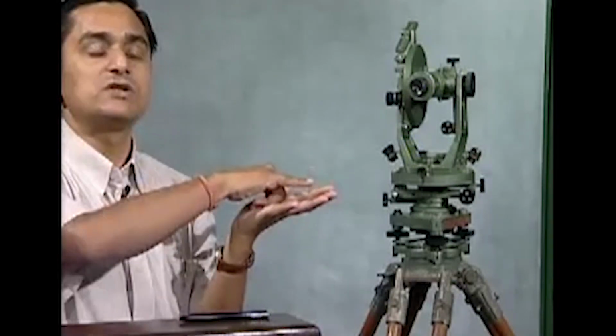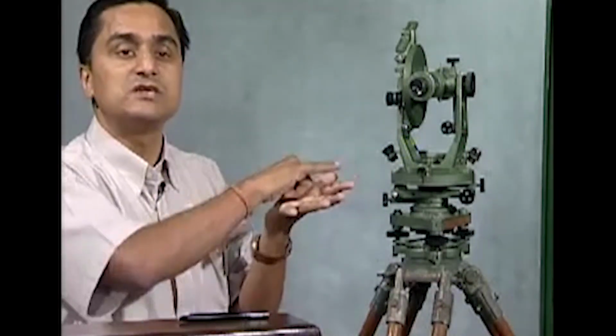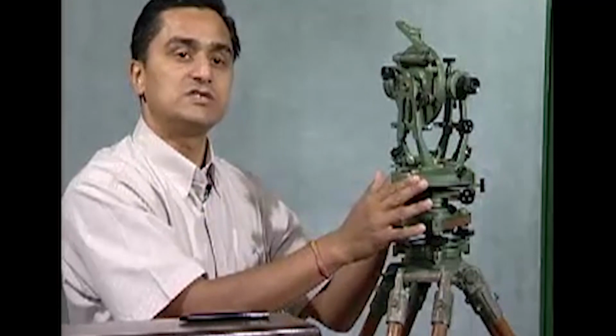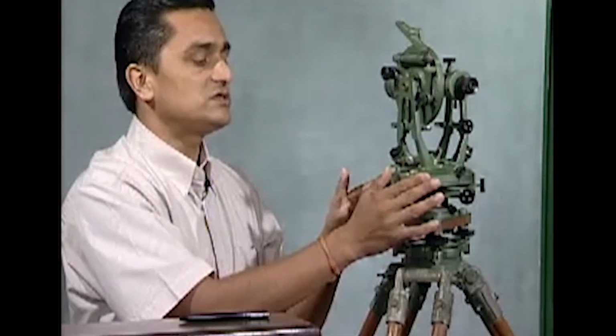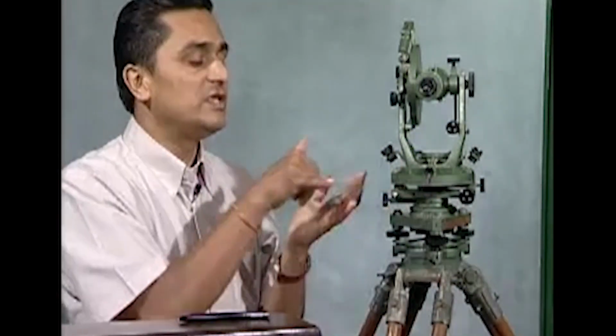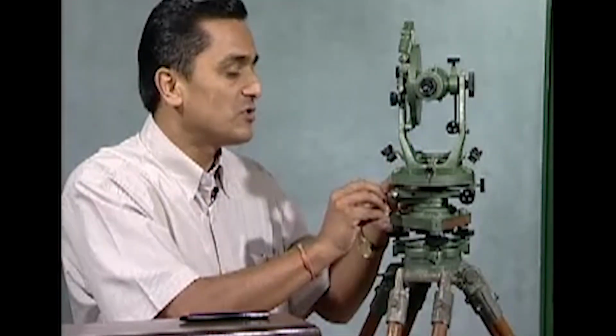The readings, these verniers, are moving on the graduated circle, and we observe the angles against these verniers. Because they are moving, the angle values are changing. So right now the lower is clamped, the upper is free to rotate, so the readings are changing. Okay, what I do, I change the readings looking through the window here, and I bring it nearly to 0, 0, 0. What is the meaning? The 0 of the vernier and the 0 of the main plate meet each other. So now at this stage, they nearly meet each other.